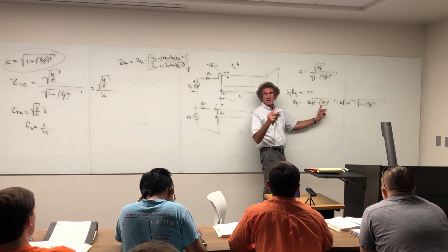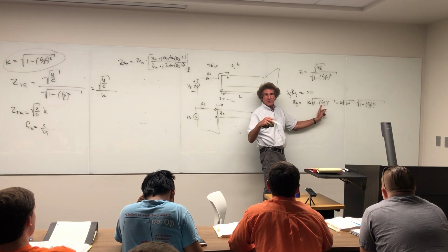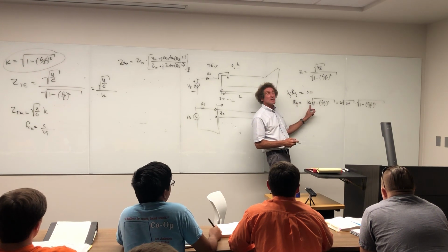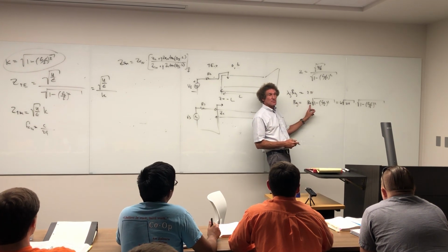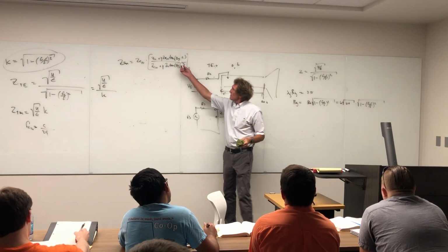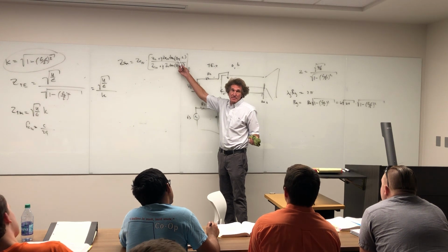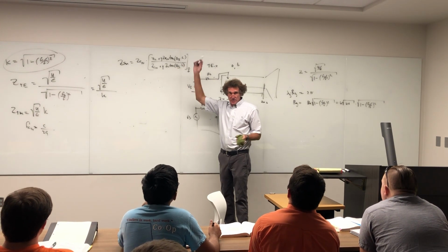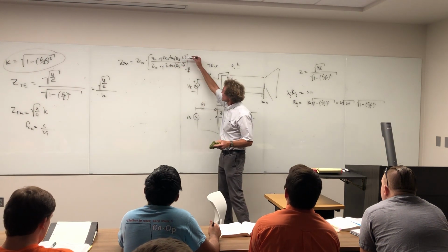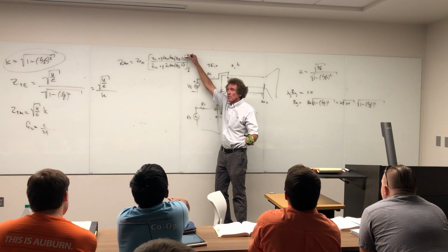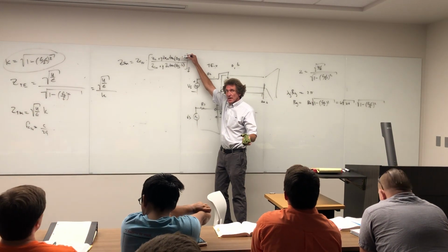As frequency gets high, it doesn't matter the mode, by the way. As frequency gets higher and higher, all of a sudden, beta goes to beta unguided, like a plane wave. Can you all see this, class? So that's what this beta in the guide is right there. It's unguided times k, if you will. How many understand what I'm talking about here? Because this equation requires beta in order to work. L would be stated explicitly, but beta wouldn't. Follow me on this? It's important.